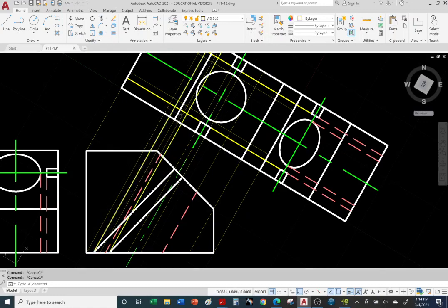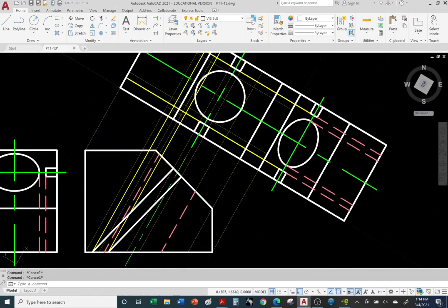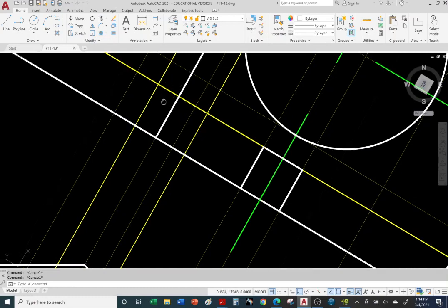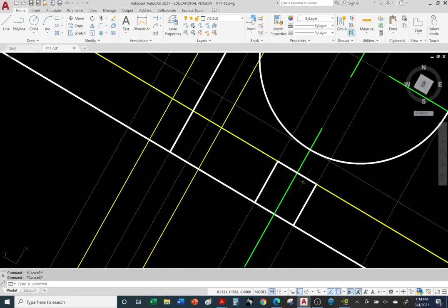These thick construction lines are telling us that this is the exit point of that slot. You can see it here from the bottom and project at this angle with respect to the center line. And there's the exit point. Let me roll in. So here's the entry point and here's the exit point. Okay, so let's draw our visible object lines.